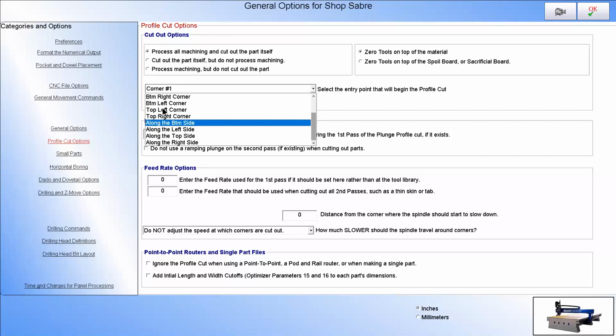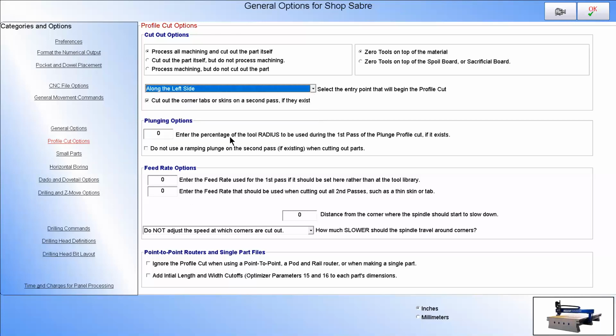What it does on these corners instead is it goes in at the angle, comes back and plows out the area that it came in on, that's equal to the tangent of that angle, and then it goes all the way around. So it goes in, back, and all the way around. This one is cleaner when it goes in along the side, because now it just goes in, around, out. But of course, it's whatever preference you have.